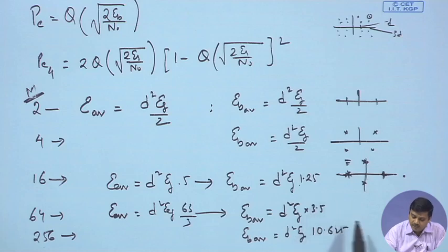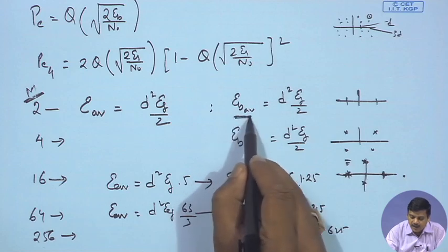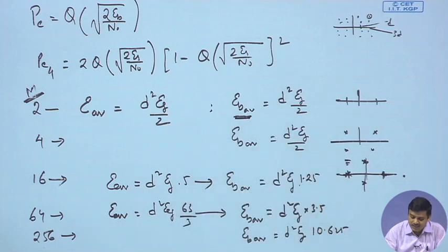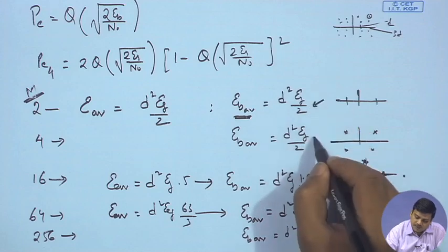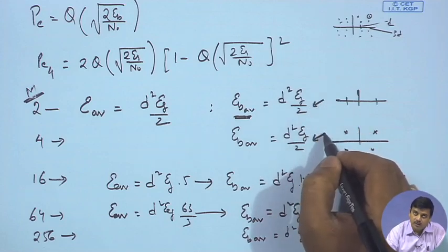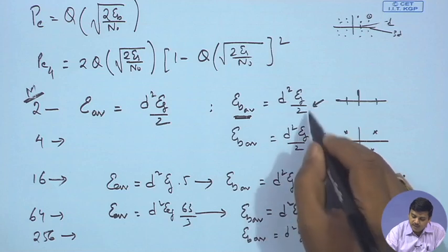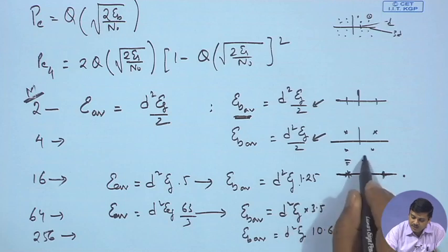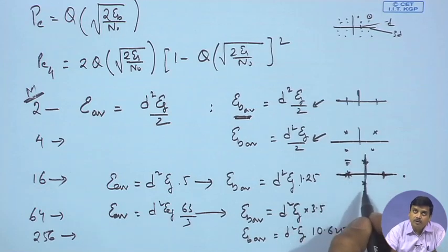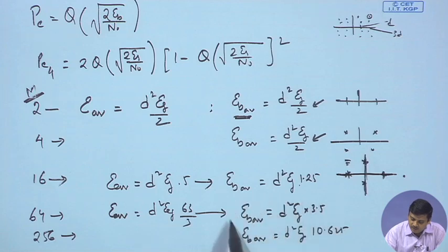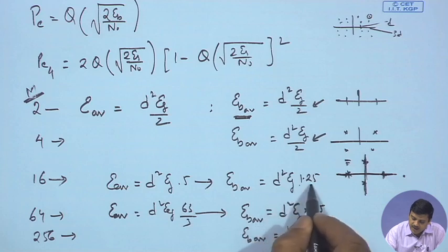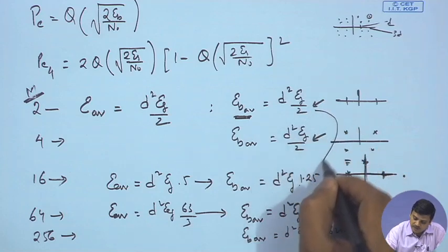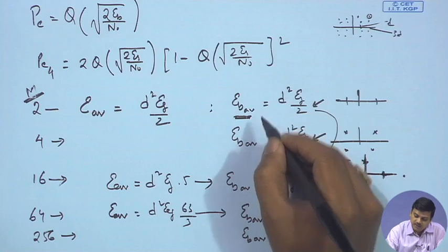So, if I have to maintain the same error probability, what we find is that Eb average keeps on increasing. Between BPSK and QPSK, that means binary PAM and quaternary phase shift keying, we find that the energy per bit requirement has not been different, and the simple justification is as if there is binary PAM on 2 axes. However, if you go to 16 QAM, the factor is 2.5 times if I compare the energy per bit required.